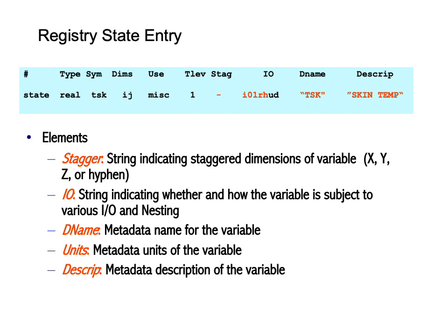This registry is an active data dictionary, so the active part refers to the information that you put into the registry that is going to be included inside the WRF model, and it's going to impact source code. For example, how many dimensions does the variable have? Is it real or is it logical? Is it a character string? Does it have a single time level? Where is the staggering? All of these pieces of information will modify the WRF source code.